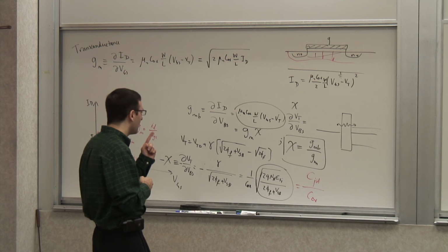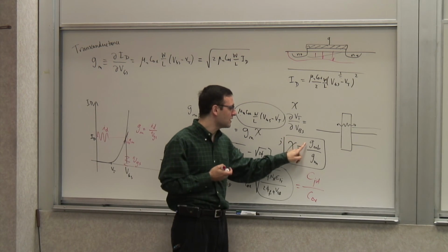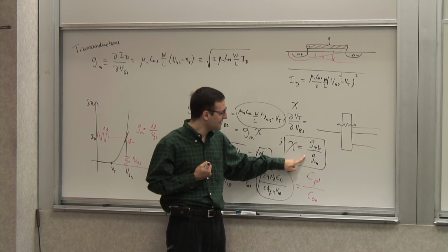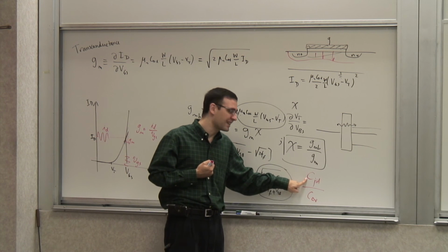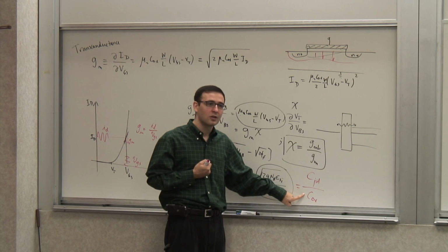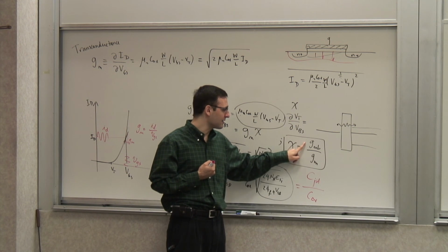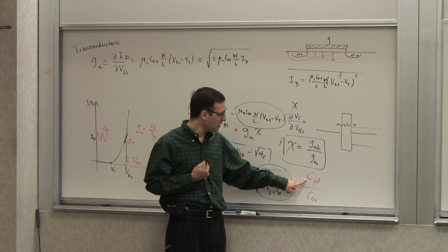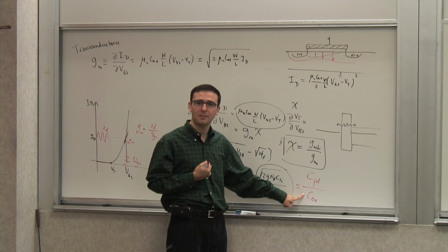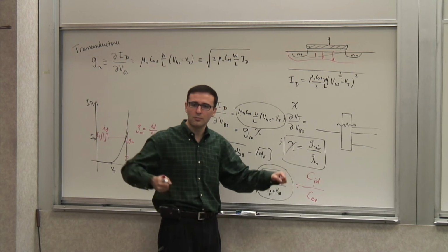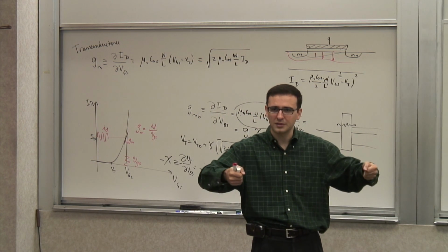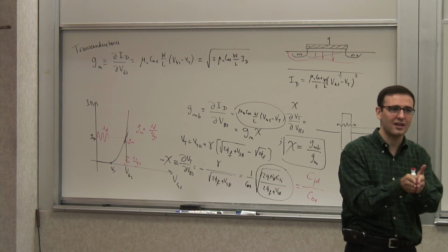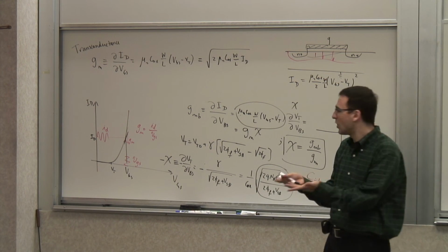So what it basically tells you is that the ratio of the strength of this bulk transistor to the main transistor is the same as the ratio of the bulk capacitance, the depletion capacitance, to the oxide capacitance. In other words, the ratio of the JFET to the MOSFET, because you're forming a JFET on the backside, is the ratio of the depletion capacitance to the oxide capacitance, which is not that surprising either, because they are both field effect devices. They're controlled through the electric field. So the one that's more strongly coupled to the channel will control it more strongly.